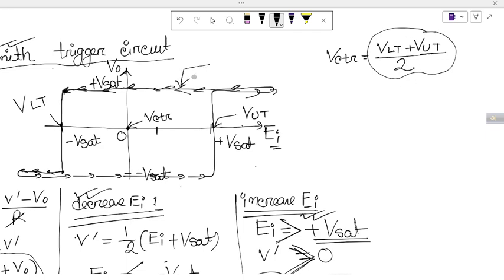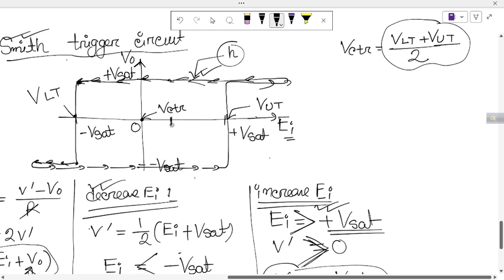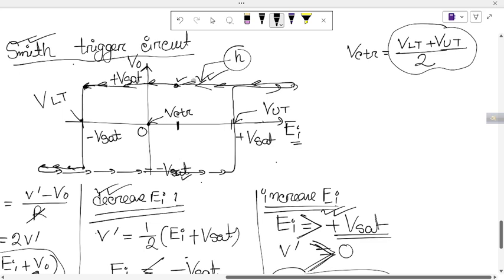And again, it is called a hysteresis graph. Why is it called a hysteresis curve? You will see that when I stand here, I have two possible output voltages, this and this. Which one I get depends on the path. If you are decreasing the input voltage, you will get this point, and if you are increasing the input voltage, you will get this point.